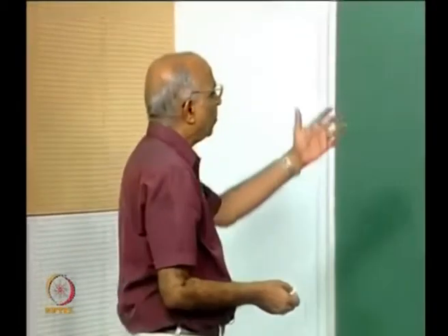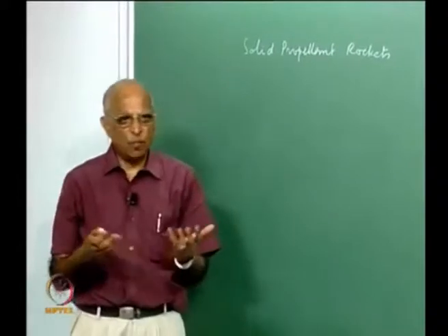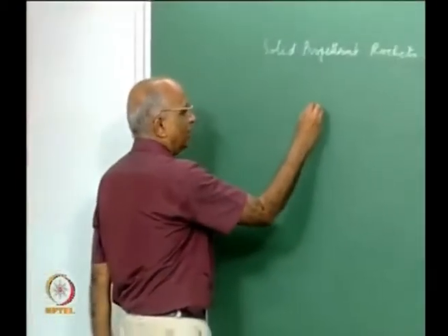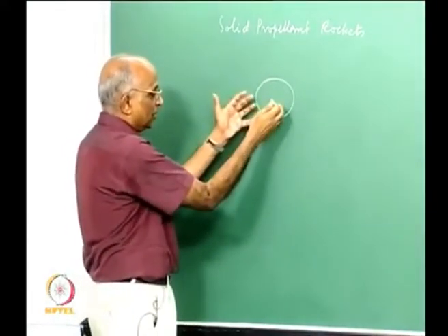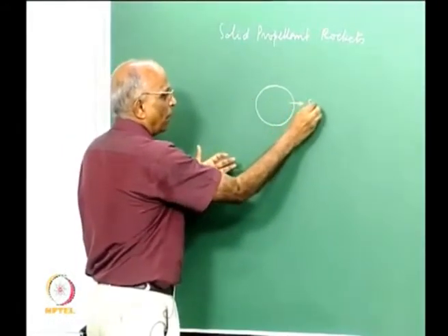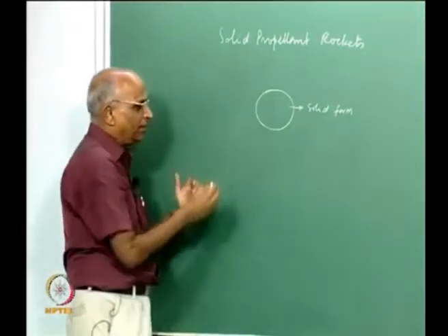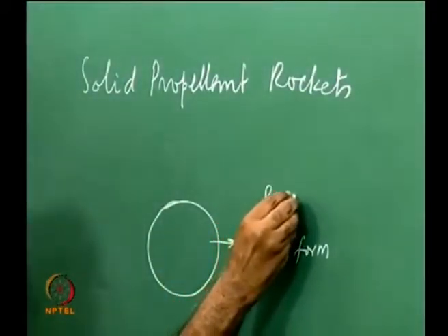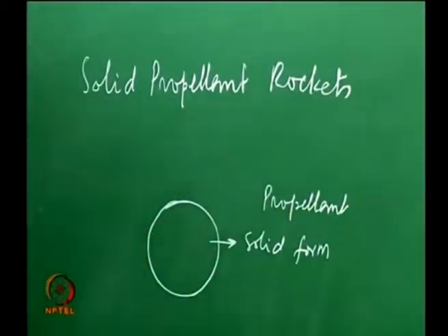We told ourselves solid propellants consist of maybe double base, maybe composite modified double base, and also we said nitroamine propellants. Whenever these propellants are there, you have maybe some base in which you cure the substances, you make it into something like a solid form, and this solid is what constitutes, let us say, a solid propellant, and we would like to use it to generate thrust.